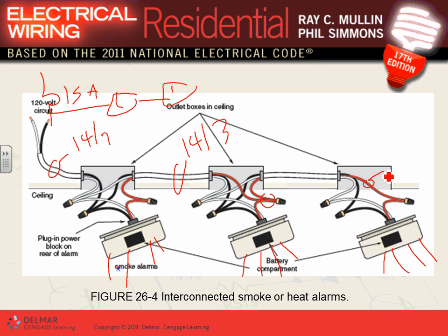Any comments, any questions, guys, on how we wire them? Do we put them on a dedicated circuit? By any NEC code book, guys, these are not considered a fire alarm system. These are power devices, right? These are 120 volt devices.